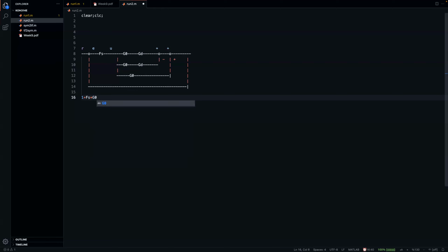Now, we're talking about a characteristic polynomial now. If we would use directly the feedback with the system with delay, then it would have the exponential term in the characteristic polynomial, which is then not going to be a polynomial at all. But with this model matching strategy that we have here internally, we're getting rid of this delay part.